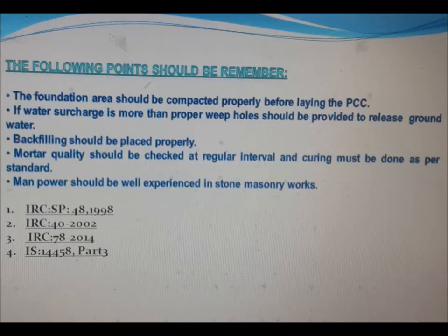The following points should be remembered during construction of banded stone masonry wall. The foundation area should be compacted properly before laying the PCC. If water surcharge is high, weep holes should be provided to release groundwater. Granular backfilling behind the wall with geotextile should be placed properly. Mortar quality should be checked at regular intervals and curing must be done as per standard. Manpower should be well versed in stone masonry works.